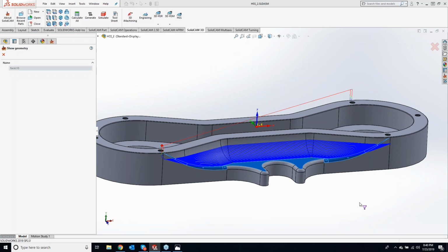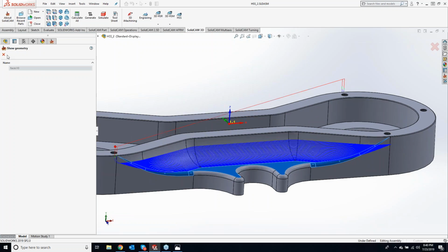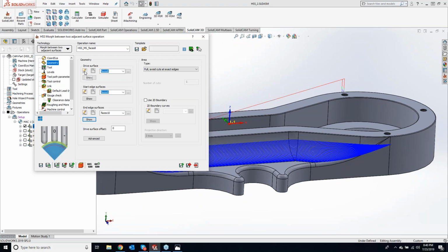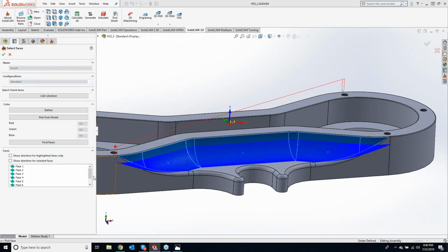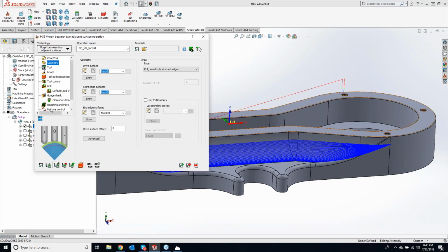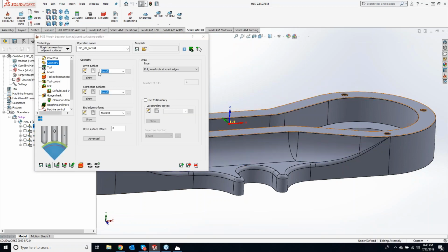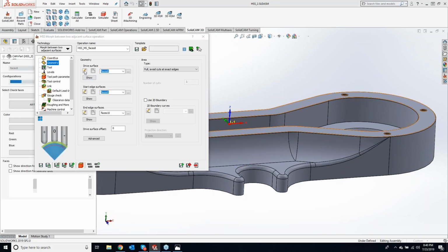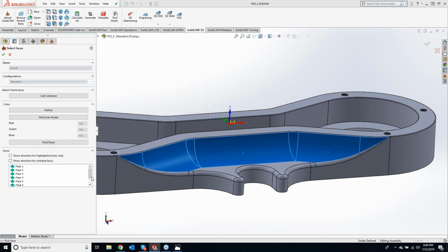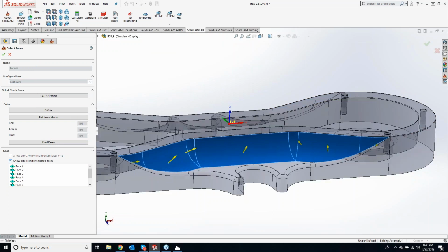And the only reason I say that is with a curve, it's just doing a projection straight up, whereas if we're doing it on a surface, what you guys can actually come into is, if I do an edit right here, and let me turn off this tool path real quick. I'll do edit. On some imported surface parts, you may get directions showing the wrong ways.